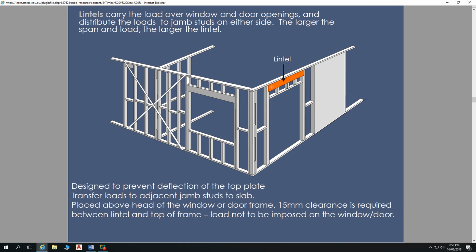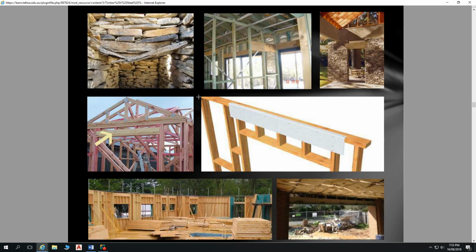So these are our lintels. So we spoke about lintels and sizing up of lintels earlier. So pieces that span over openings. Here's an example of a very old timber lintel in a stone building. So it's not just in timber frames that we use the terminology lintel. So we can have stone lintels. A lintel is a member that helps support a section of roof that's under load. So all different types of lintels. So there's a lintel here above this opening here, timber lintel in stonework.